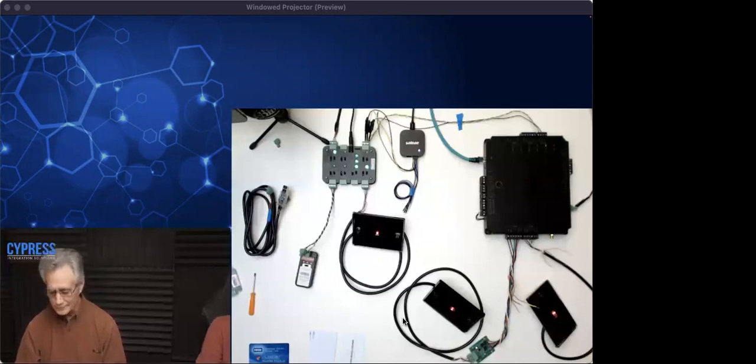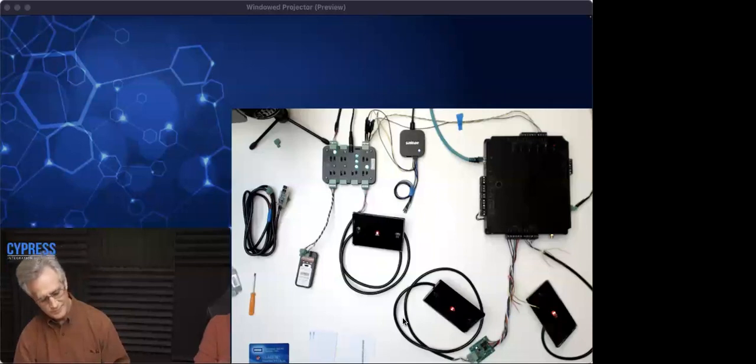Yeah, in that circumstance, Wiegand is limited to 500 feet compared to OSDP, which is 4,000. Yep, 4,000 feet. Cool. In that case it is a different converter. That'd be more like our OSM 1000 or our OSM 2400 compared to the CPI. Correct.